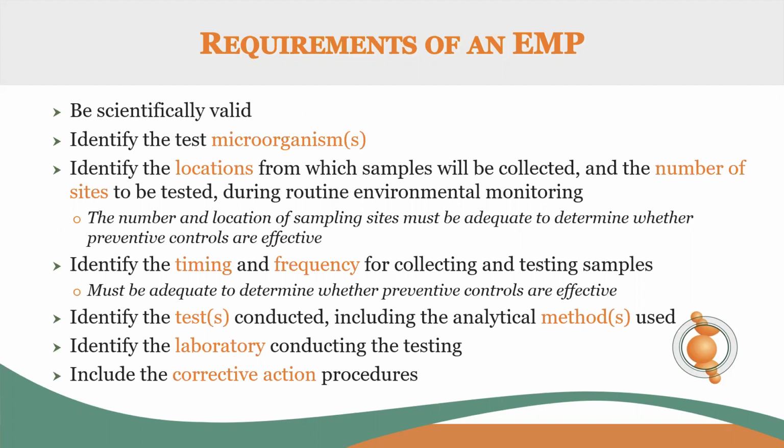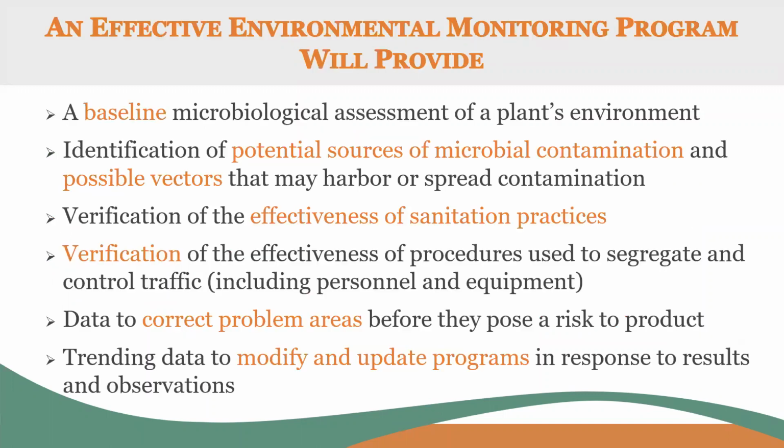It must identify the timing and frequency for collecting and testing samples. It must identify the tests that are to be conducted, including the analytical methods that will be used to perform these tests. It must identify the laboratory who will be conducting these tests. And then it also should include corrective action procedures if there is some sort of issue that arises from this testing.